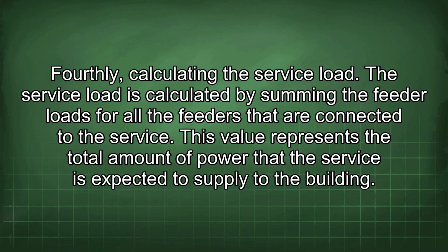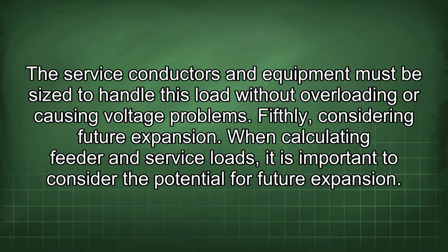The service load is calculated by summing the feeder loads for all the feeders that are connected to the service. This value represents the total amount of power that the service is expected to supply to the building. The service conductors and equipment must be sized to handle this load without overloading or causing voltage problems.